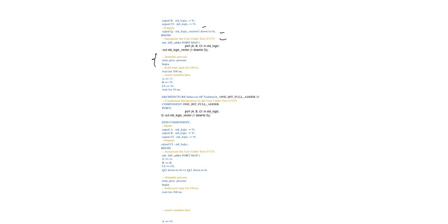In the architecture declaration we have defined all the inputs and outputs, and next input declaration with signal data type, and next output declaration with signal data type, initialization of unit under test. This is your port declaration, and the stimulus process starts from here, and we have taken 100 nanoseconds because the question mentions 10 megahertz. So at 100 nanoseconds we describe all the input variables here, and the architecture for test bench for 1-bit adder. Again the different signal values are given. So this is a standard UUT method.